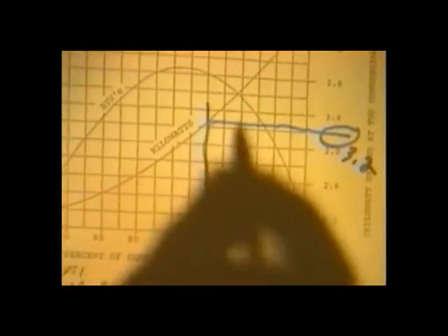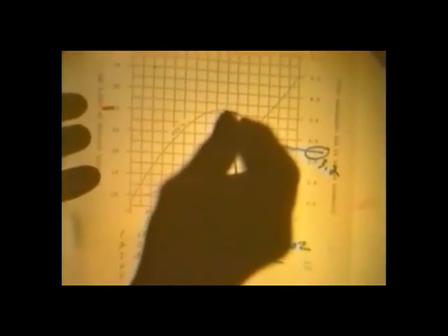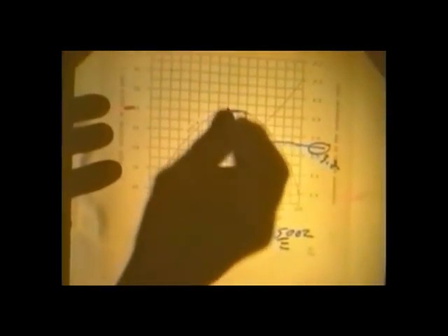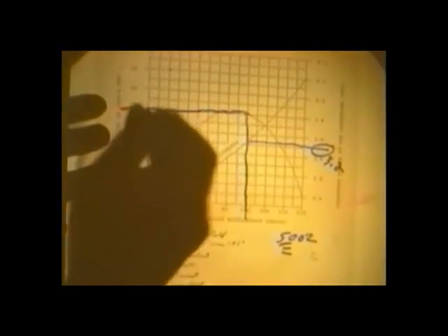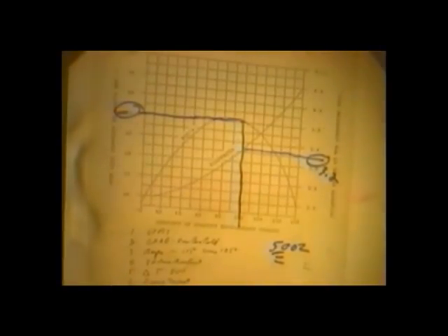But I'm going to continue this line up to our BTU line, and it's going to show about 26,000 BTUs. So in this particular example, with a 50-ounce charge, we've got a 26,000 BTU AC system. The kilowatt demand is 3,200 watts, 3.2 kilowatts, okay? So we're okay with that, right?